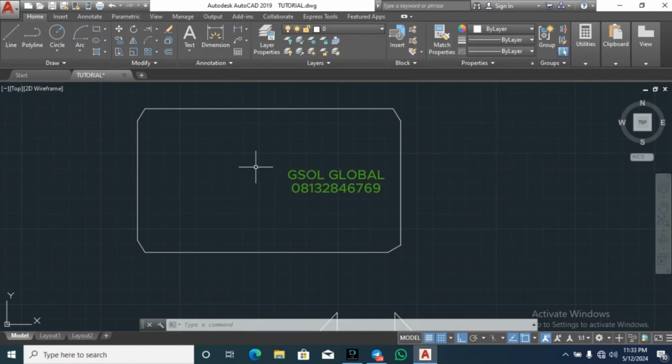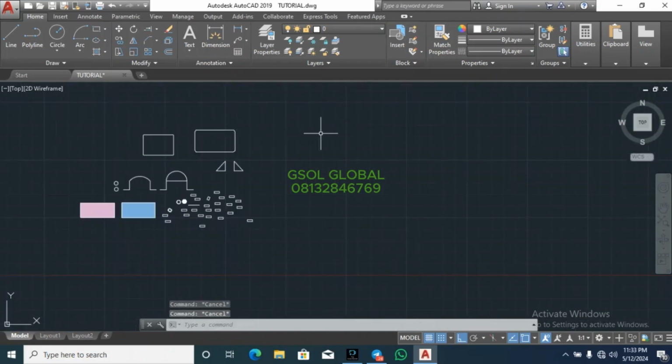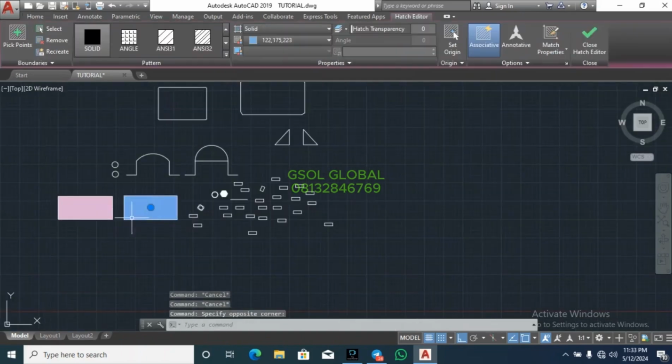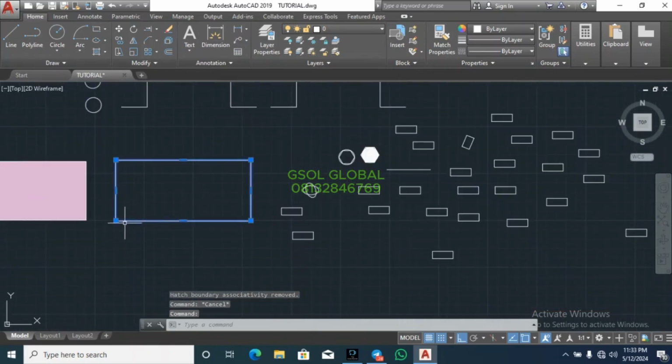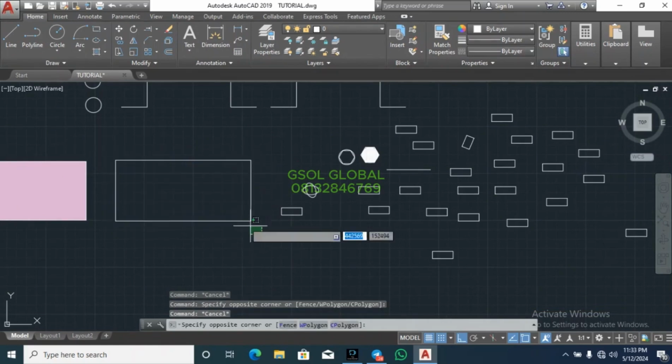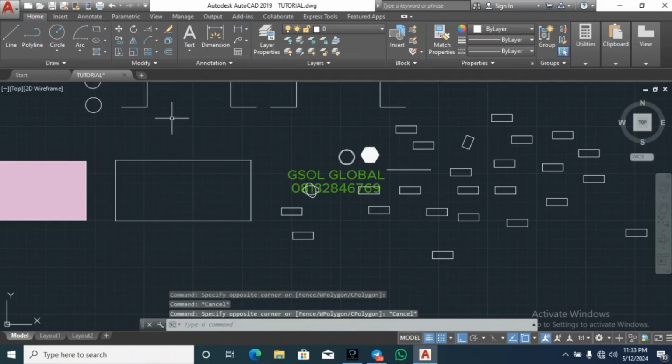All right, so now the next one we have here is explode. Explode is used, as it implies, to explode group objects into single objects. To explain this, let's go to the group object we have here. Let's do this, erase, enter. So these are group lines. Let's assume that I want to explode a group object into single elements so I can select them properly and easily.